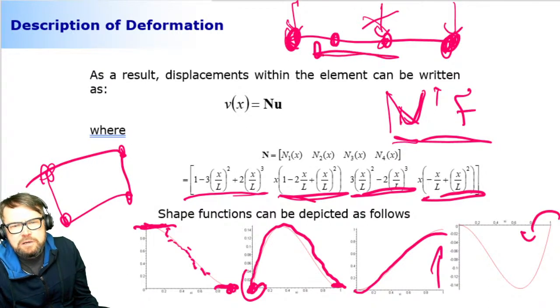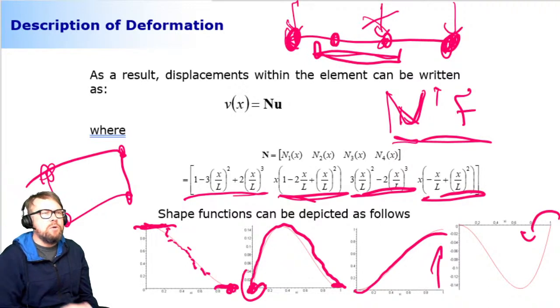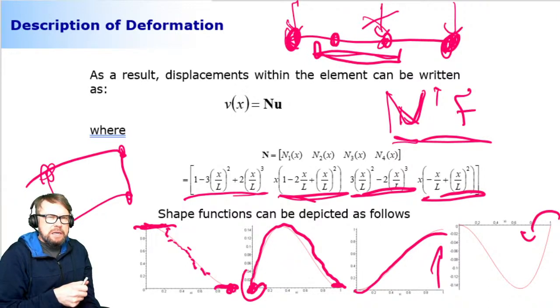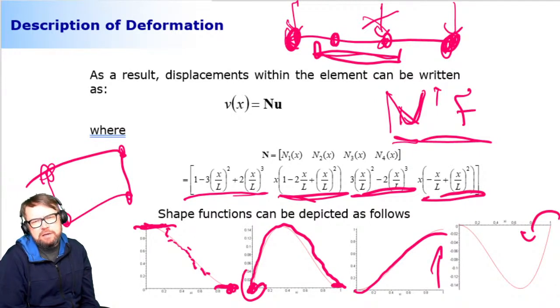When you have these internal nodes, the computation will be heavier. So they can increase the accuracy at the expense of heavier computing. But typically they increase the order of the polynomial, which is capable of predicting more complicated behavior. So it's kind of recommended to increase internal nodes.